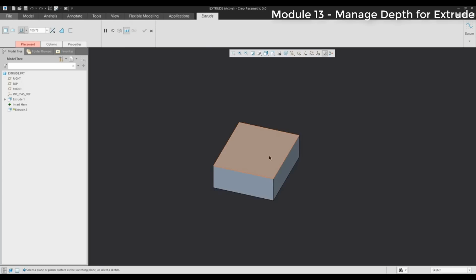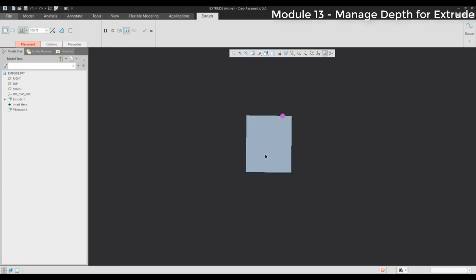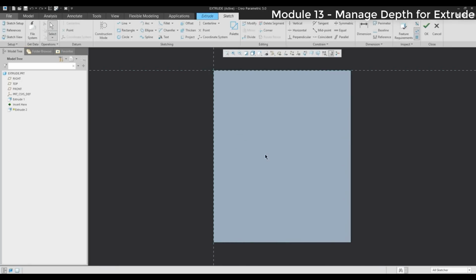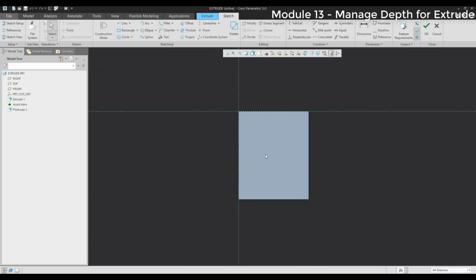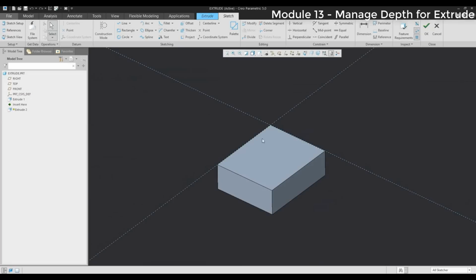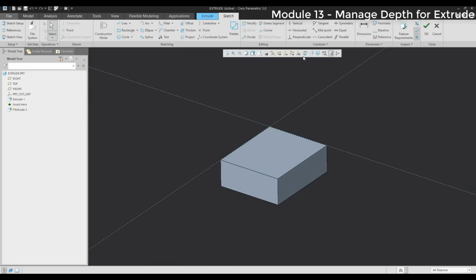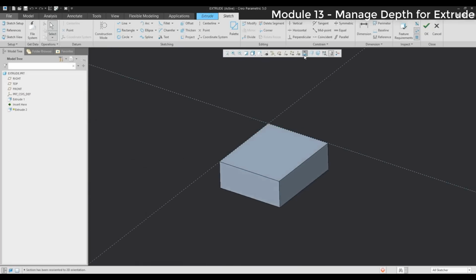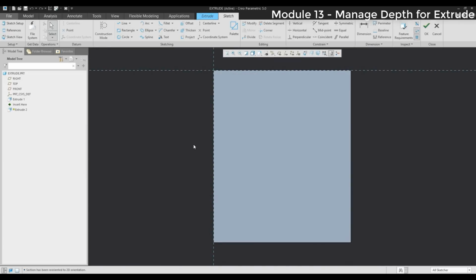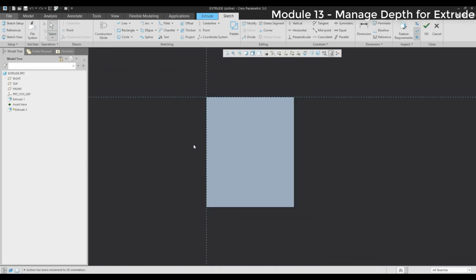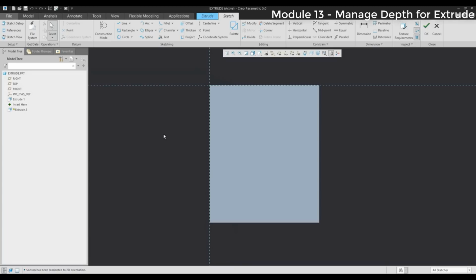If you select Extrude feature and you select a sketch plane, the system will automatically orient to 2D. It's no problem. You can jump to 3D, you can spin the model, and if you would like to jump again to 2D, just select sketch view. You can continue with creating another sketching geometry. So for example, I'd like to create another base shape and set some value.